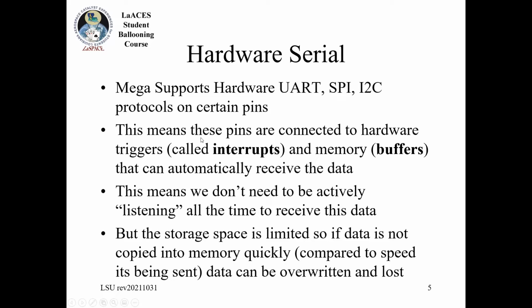What that means as far as the actual hardware is, there are triggers on those pins that will see when a clock pulse or a data pulse happens, and that'll trigger the microcontroller to do something. It can jump outside of the program to go handle that.